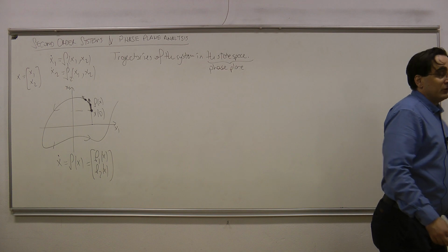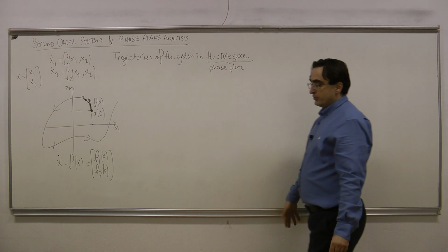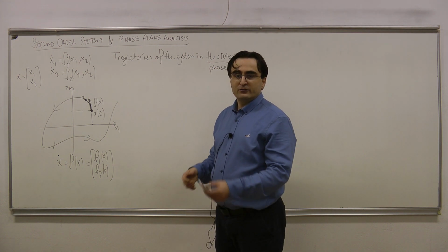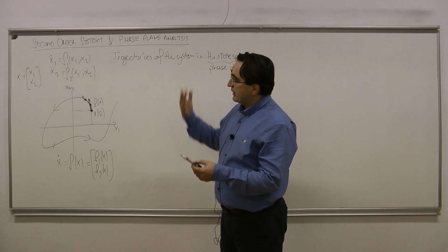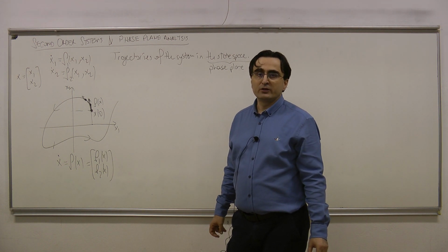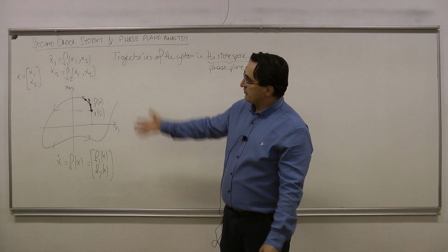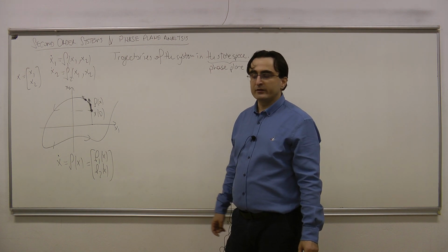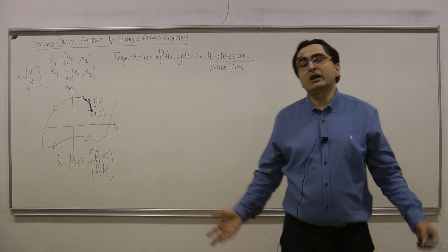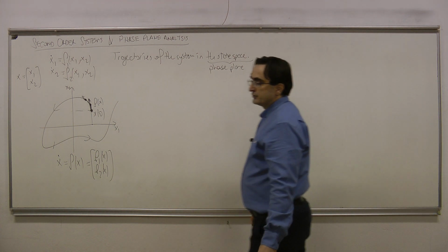Okay? So phase plane analysis is good. It gives us the analytical way to work with these trajectories, but we're going to see that it's going to be really simple nonlinear systems that we can deal with using phase plane analysis. If the functions f1 and f2 are too complicated, then we would have to resort to the use of a computer at the end to obtain complicated trajectories.